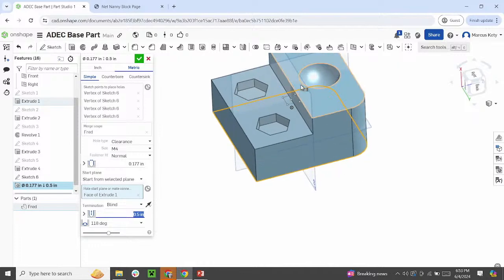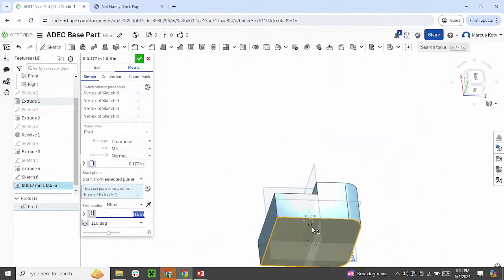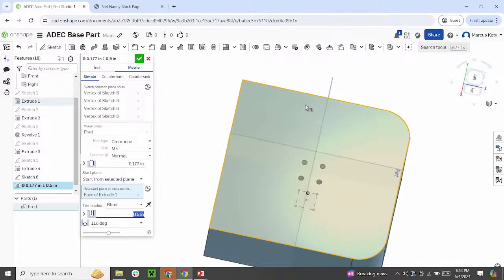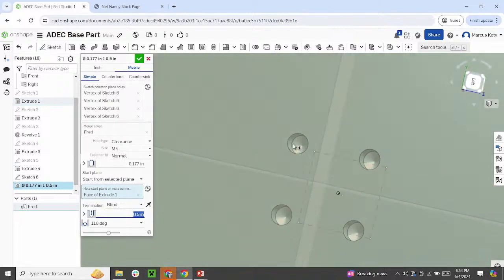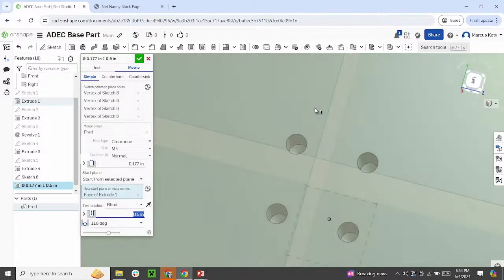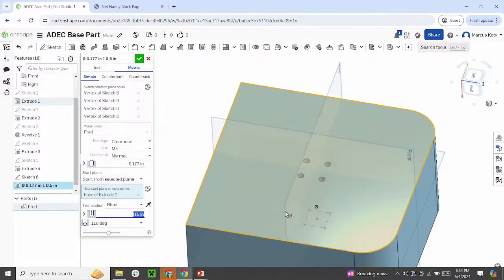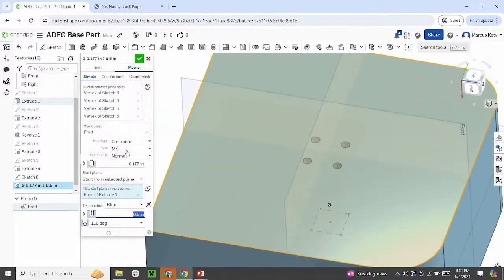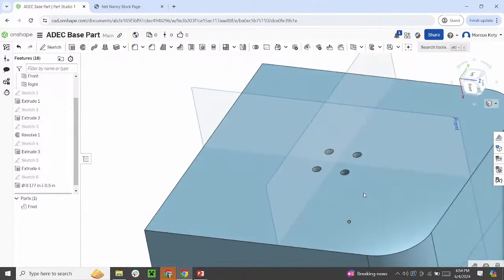I can choose a depth, 0.5. From this plane, you can see I no longer can see the bolt holes there, and they can go through here. They will always have this drill angle by default in it, because if you're manufacturing this out of a piece of metal or a piece of wood, to get that hole, you're going to have a drill, and that drill is going to have some kind of angle to it. It won't mess up your print if you leave it that way. It's fine. If we wanted to, let's go ahead and select this. So we're good to go there.